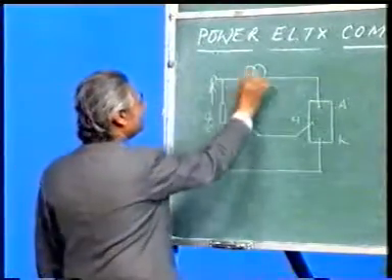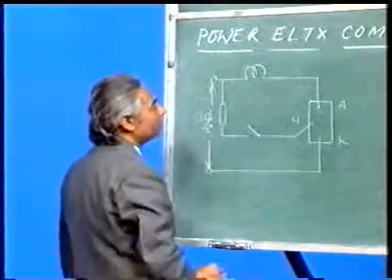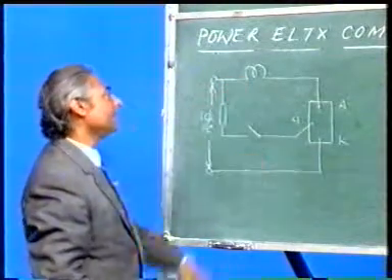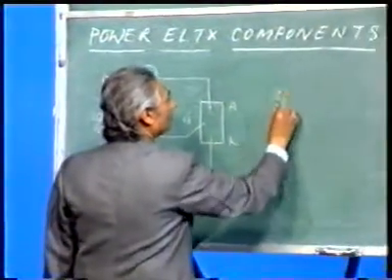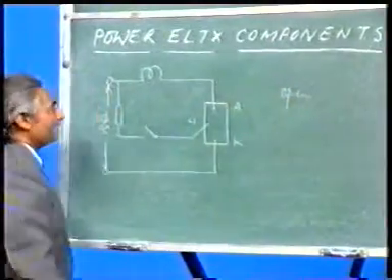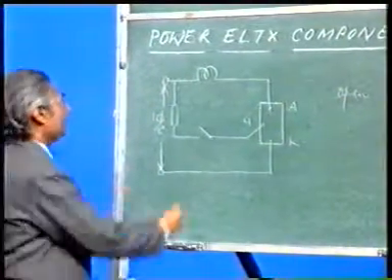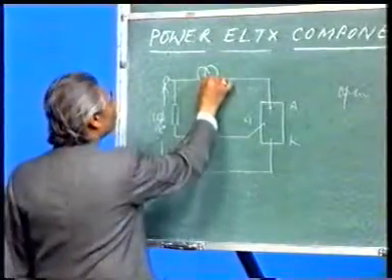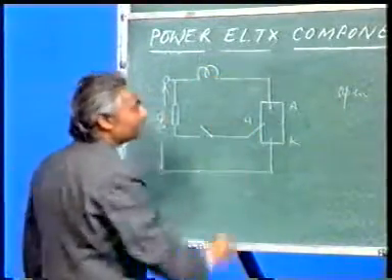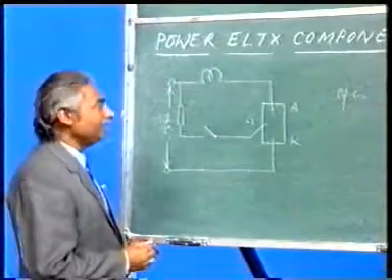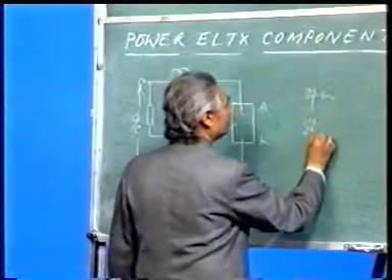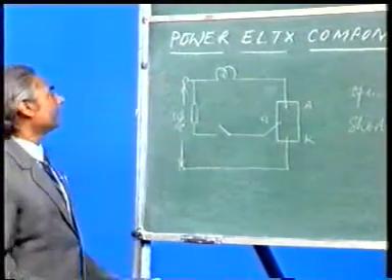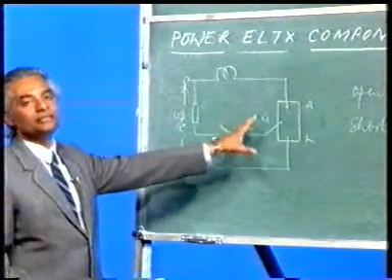Suppose on connecting this and putting this switch on, the device does not conduct, the bulb will not show any glow, that means the device is open. And there could be another condition, when I connect it between anode and cathode, I have not connected the switch, yet the bulb glows, that means the device started conducting. What does it mean? It simply means the device is short. So, a very simple electrical circuit with the help of which you can test the health of an SCR.